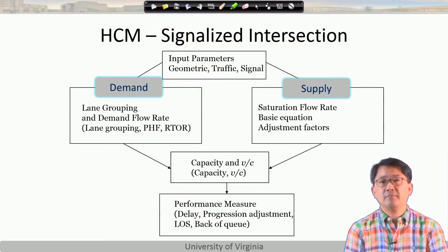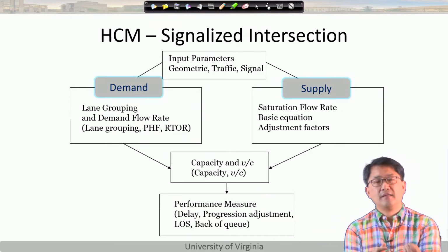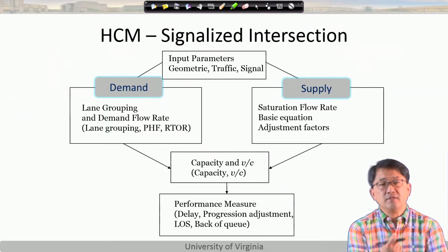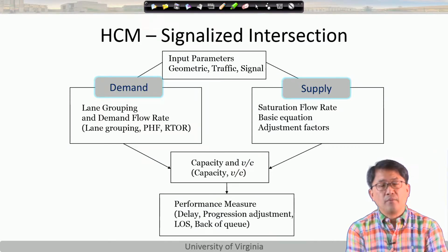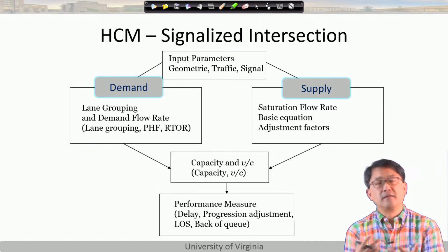It could have been a minute, but they decided to have 15 minutes as a good interval for collecting cars back in probably the 60s and 80s. And using that information, they are trying to look at the worst 15 minutes. And they want to deal with the worst 15 minutes happening for the entire hour. Part of the reason is that if you have 4 different approaches, having 8 different turns, like throughs and right turns, each has a different 15-minute peak.